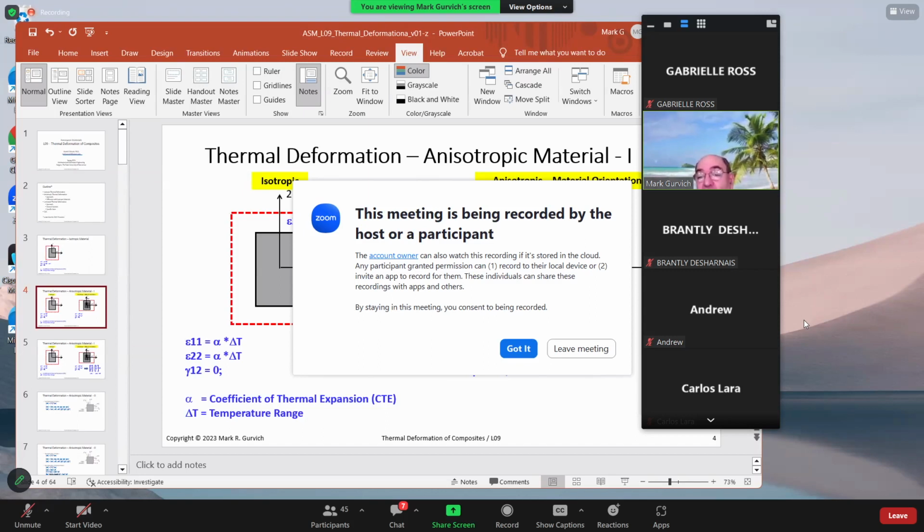So obviously, thermal expansion properties of fibers are different than thermal expansion properties of polymer. And because fibers are in orientation 2, like in this example, here we would have properties primarily driven by CTE of fibers. In orientation 1, it will be thermal expansion primarily driven by polymer.